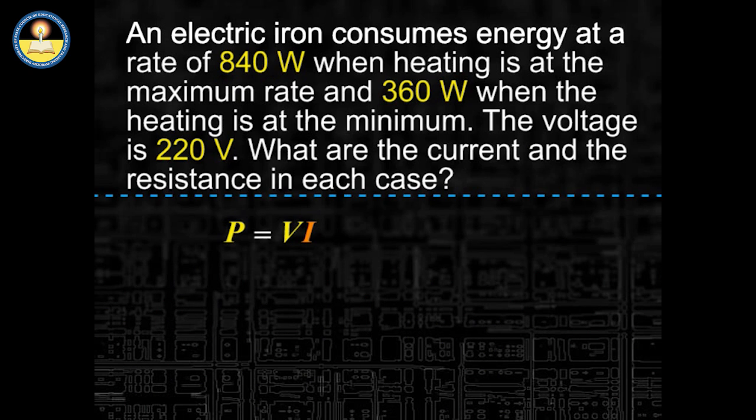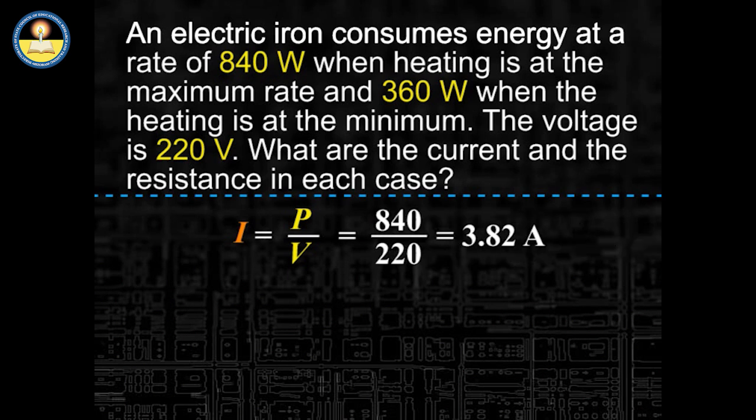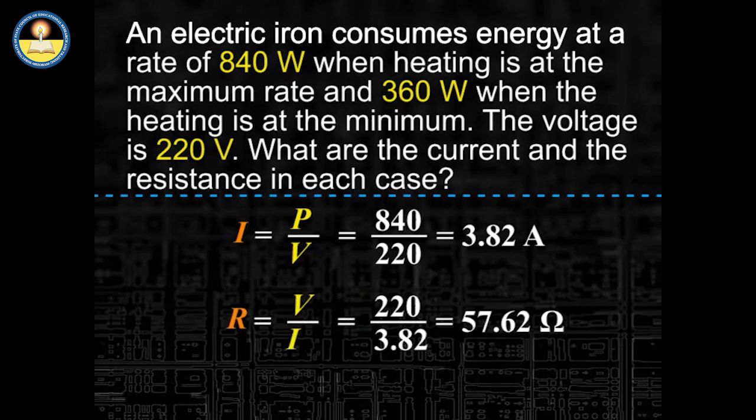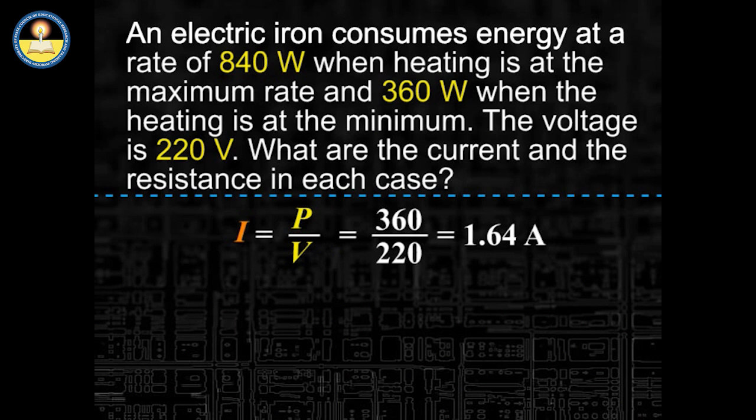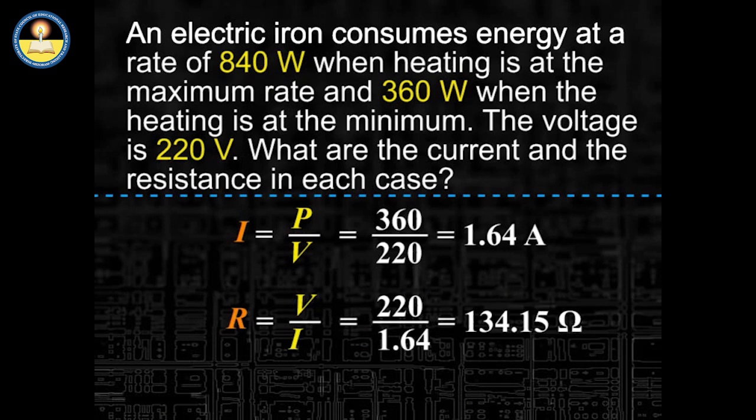Let us have a look at another combination in which 2 bulbs A and B are in series and bulb C is connected in parallel to B. If the filament of the bulb C is broken, the bulbs A and B would continue to light up, but the brightness would decrease because it becomes a simple series circuit, and hence the effective resistance of the circuit increases. On the other hand, if the filament of the bulb A is broken, then the bulbs B and C both would not light up at all.